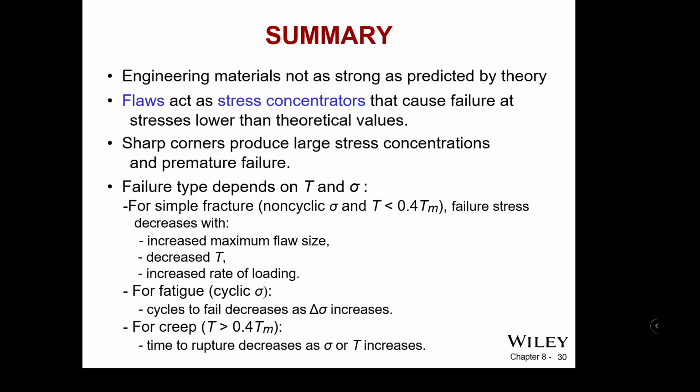So a lot of things in practice are not as strong as the theory would just blindly predict, and that becomes very important for a lot of reasons. So the flaws act as stress concentrators to create a failure because the stress is much higher at that concentrated point than what a theoretical value would say.